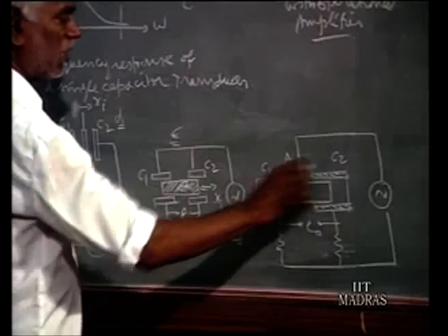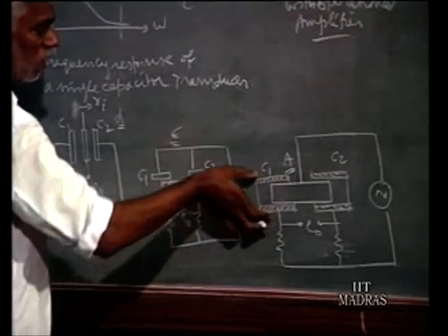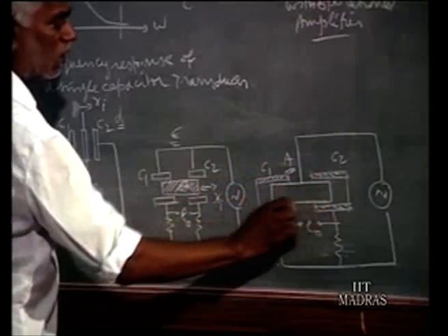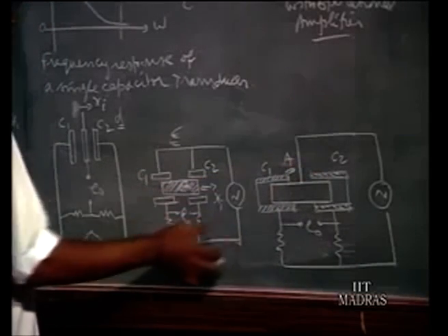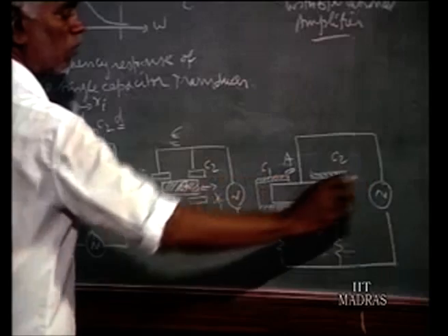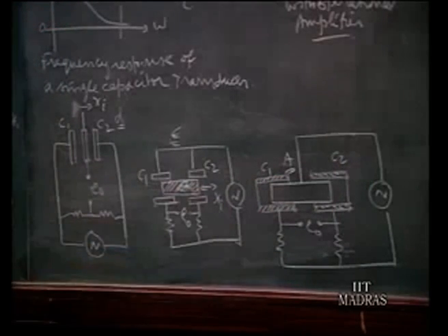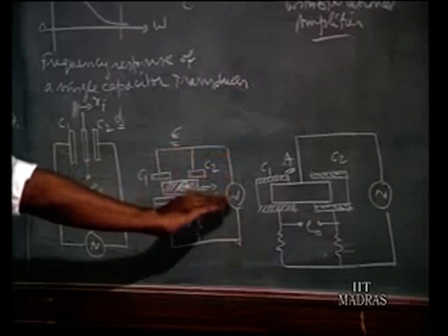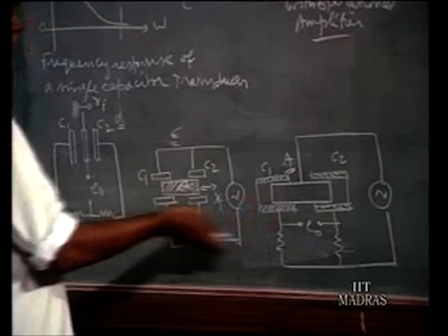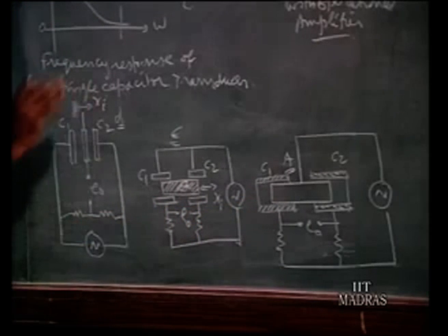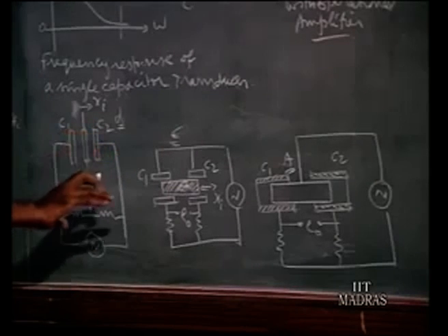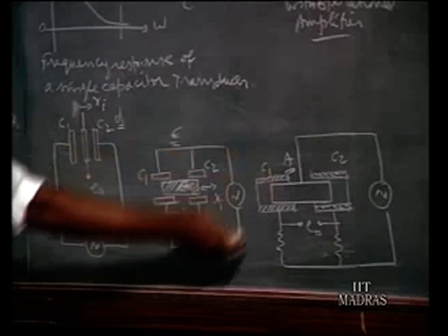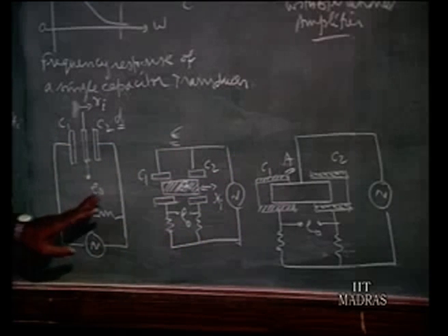Similarly, by having a cylindrical construction for the plate, this is cylinder 1, cylinder 2, and this is a rod, having a common area equal in both to start with. Later on, if you move to the right hand side, C2 will increase in area, C1 will reduce. So they are connected again as adjacent arms of an AC bridge with the excitation and so forth. The output voltage, we know, is a modulated one; we can amplify it, then a phase sensitive demodulator and low pass filter, all these things are understood. I am not doing these here. By using a carrier frequency amplifier we can read the output voltage corresponding to this.